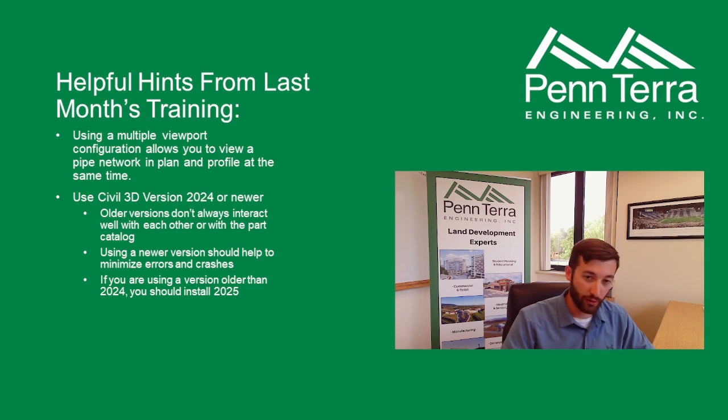So to get started, we're going to review a couple things quick from last month, since last month was kind of an intro to pipe networks. So the few helpful hints. You can use the multiple viewport configuration if you need to view plan and profile at the same time, or if you're working on, in this case, storm charts at the same time as seeing a plan view or a profile view. It can be really useful.